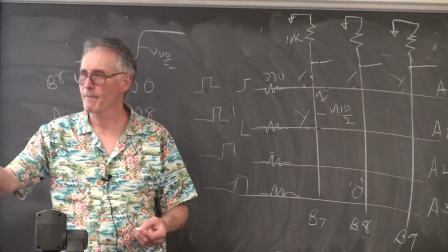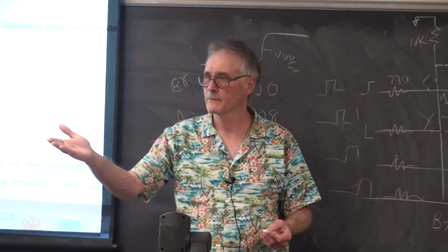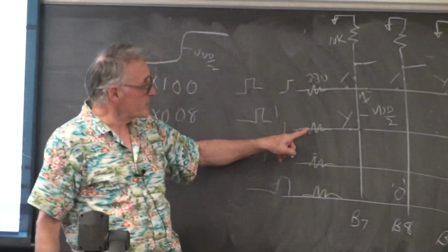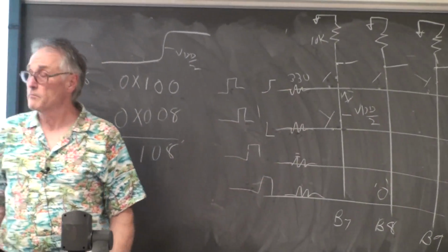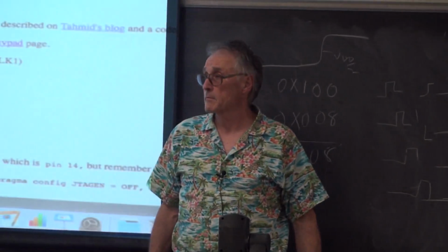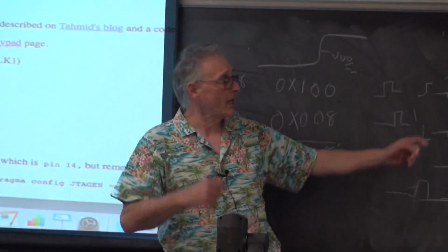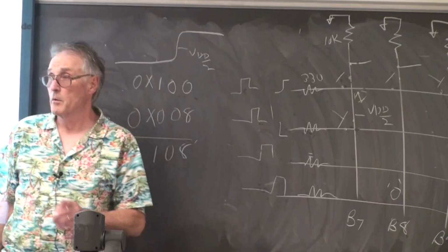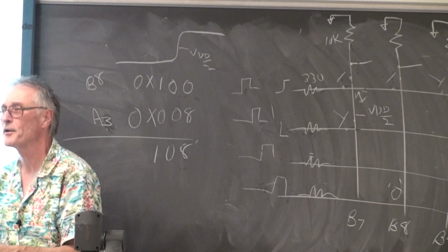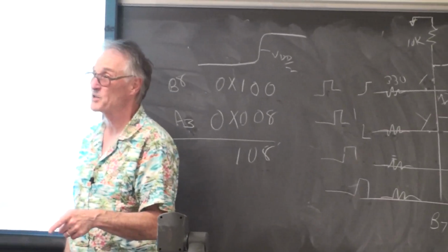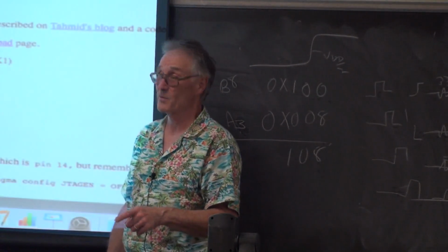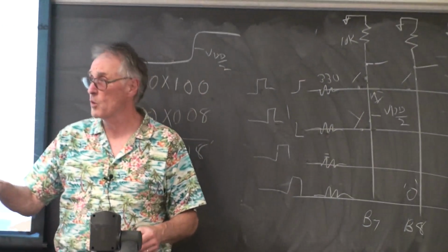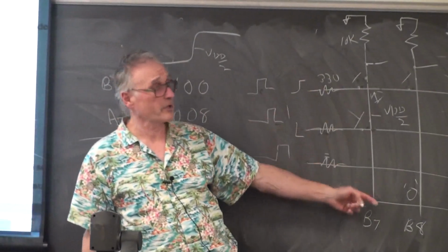I was wondering, can you just change the other pins to high impedance? So you could, for instance, just float the other inputs? Sure. Yes. You could do that. You could dynamically make one an output and float the other ones. If you do that, put the 300 ohm resistors in anyway in case you mess up the code, because otherwise you'll blow the port. But yes, you could do that, and that simplifies it somewhat. That makes the error checking vertically very robust.